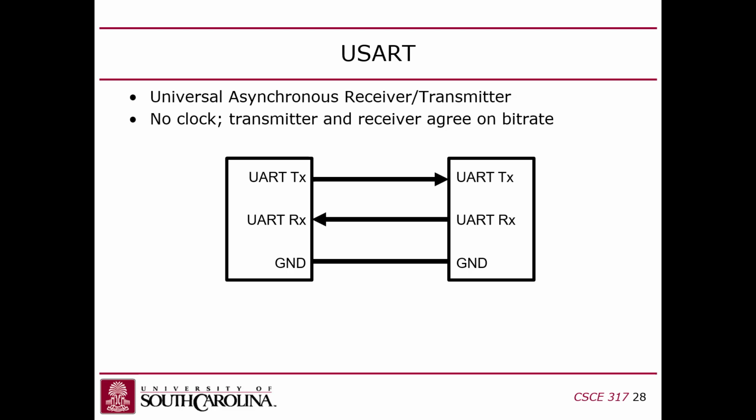One of the things about UART that's a little problematic is that it's asynchronous, meaning that there's no clock signal as part of the bus wiring. So each of the endpoints here have to agree somehow on the speed, on the bit rate. Which kind of stinks, because if you buy something off the shelf and it has a UART port and you want to plug into it, you have to figure out what the speed is, otherwise it won't work. And oftentimes that just involves trial and error, unless you can read it off the instructions. But who reads instructions?